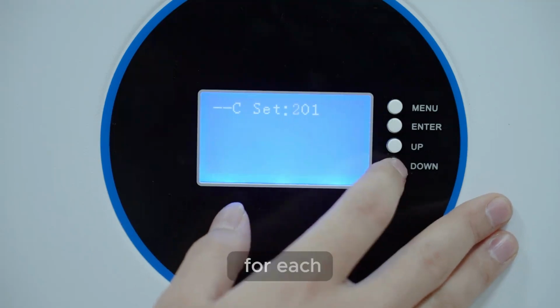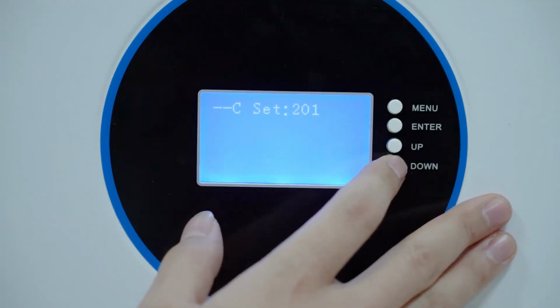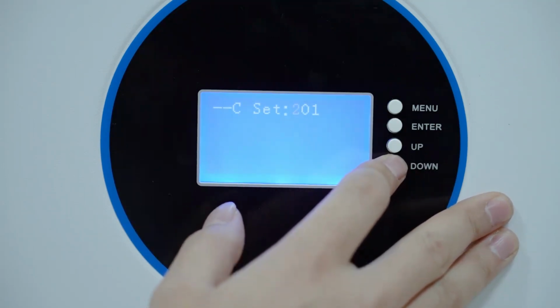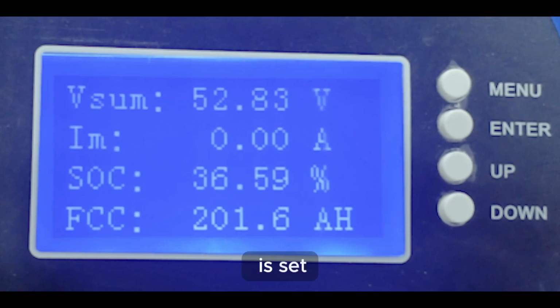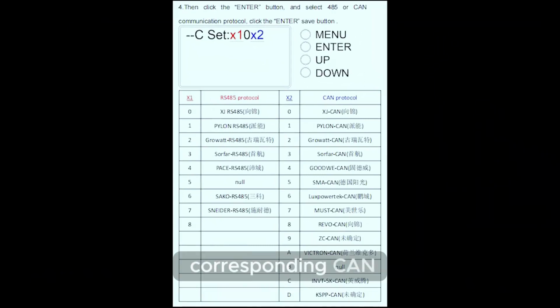Corresponding settings for each brand inverter are listed in the table. If the inverter uses an RS485 communication port, set the number of the corresponding 485 communication port in the list. If the inverter uses a CAN communication port, set the number of the corresponding CAN communication port in the list, as shown in the figure.